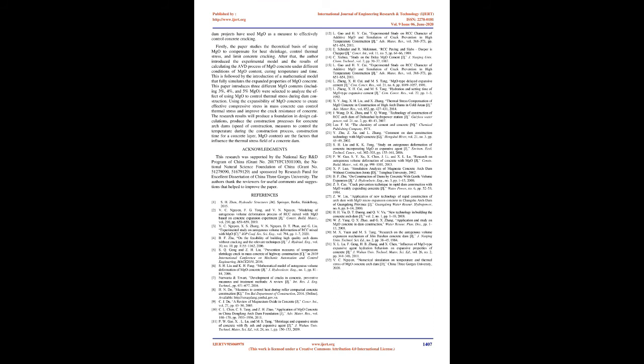This method makes full use of the delayed micro-expansion characteristics of MgO to reduce or compensate for thermal shrinkage deformation of concrete, reduce the tensile stress of concrete dam, and then effectively reduce the possibility of dam cracking. So far, many concrete dam projects have used MgO as a measure to effectively control concrete cracking.